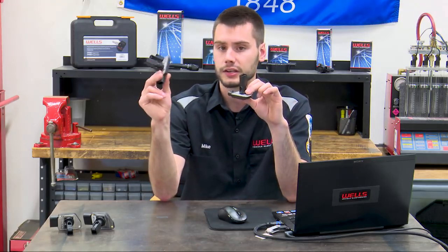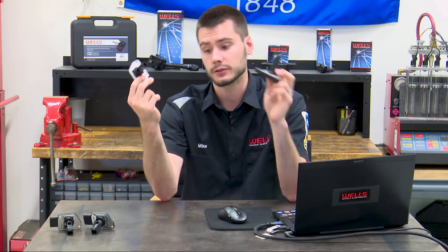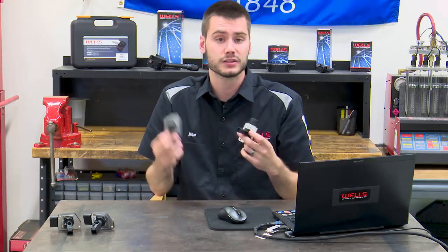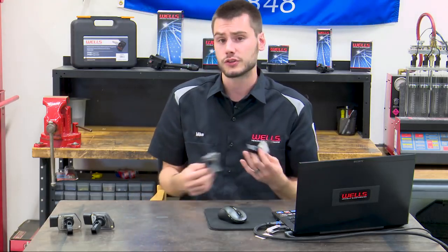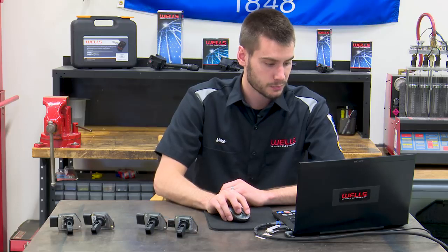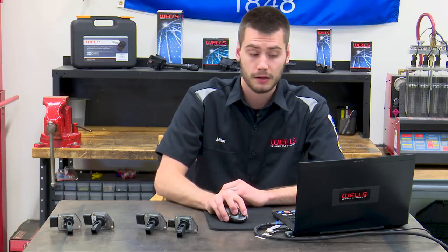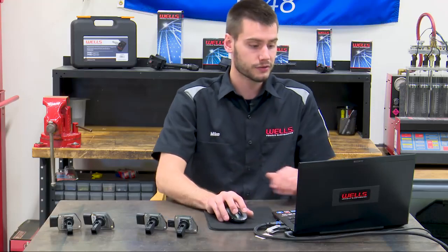So here, the Colorado sensor I cleaned with mass airflow sensor cleaner, and the GTO sensor I cleaned with brake clean. If you remember from the last class, we talked about the different cleaners and if you should clean them or if you shouldn't, and what carb cleaner does to them. And we kind of determined mass airflow cleaner and brake cleaner were kind of the way that you would want to go. So that's what I did. I took and sprayed them down and took some images on the microscope.